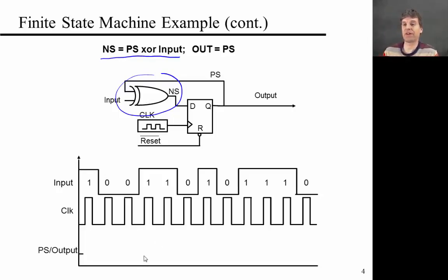So the diagram here at the bottom is just trying to make it intuitive how to think of these circuits that are now sequential, right? And so we have to go essentially clock period by clock period. So I'm just going to look, assuming that my flip-flop is positive edge triggered.